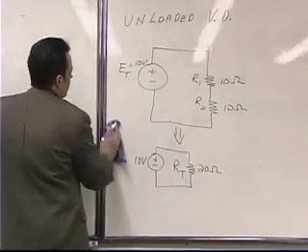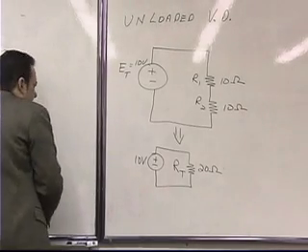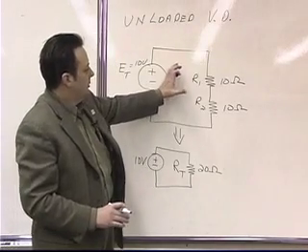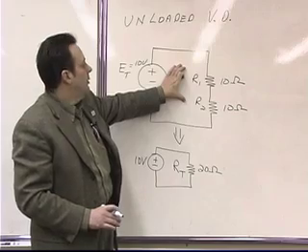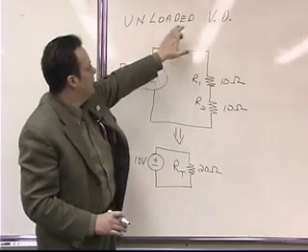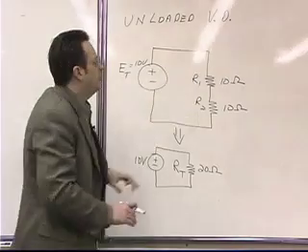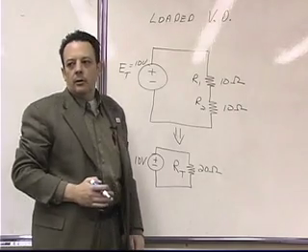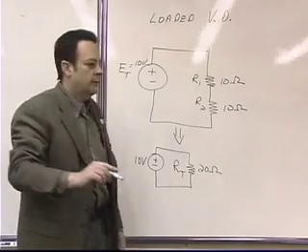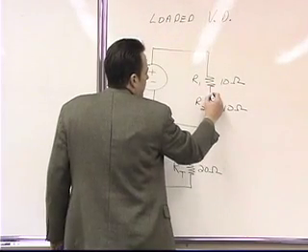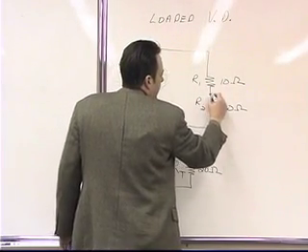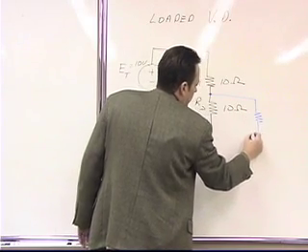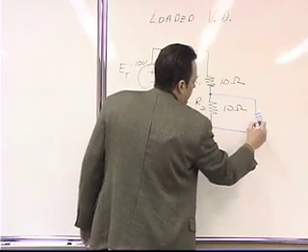I'm going to switch colors here to blue, and I am going to transition this voltage divider from an unloaded voltage divider to a loaded voltage divider by doing one simple thing, and that is taking another resistor and placing it in a parallel connection with the bottom resistor in our first circuit.